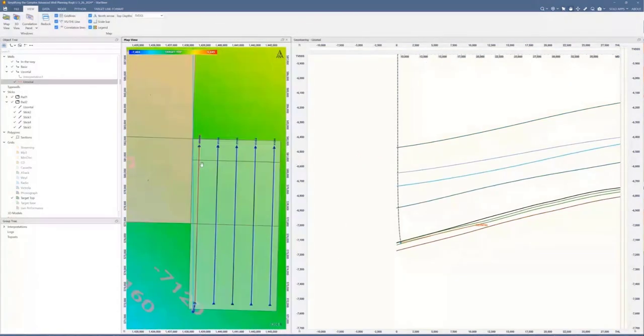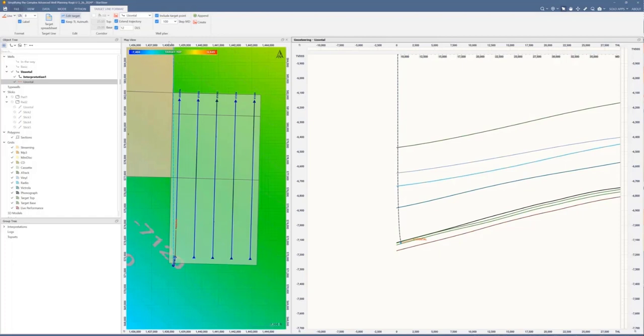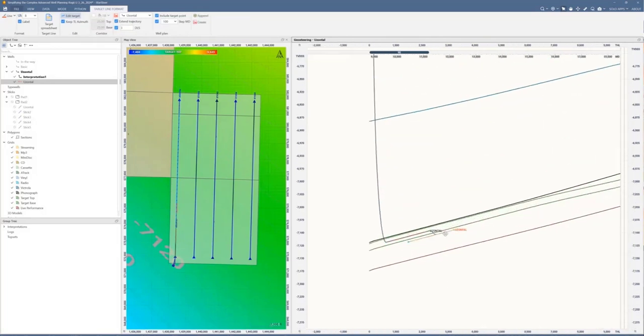Okay, so I had mentioned we have this horizontal line here. So let's start planning our well, but let's make sure that we stop at a certain point, okay? So I'm going to take this green dot here and bring it back. I'm going to shorten it up to about here. And I'm going to go into this target line format here and hit append. And because we're now in the lateral section, I'm going to knock the dogleg severity from 12 to 3. When you hit append, it essentially locks that segment in place, and then it makes a duplicate target line on top of it.